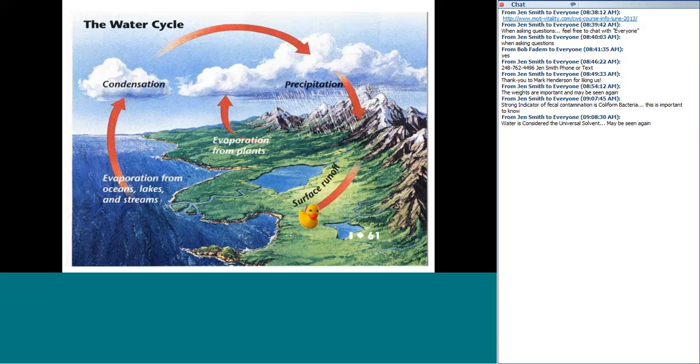We even have neutralizing. So those of you out on the East Coast that run into acid water or low pH water, that's basically when the water is acidic. It comes down from the clouds acidic because of the carbon dioxide levels, and in most areas in the country, you're neutralizing that water by running it through calcium and magnesium, which brings the pH back closer to neutral. That's basically the same thing that you're doing when you're running it through a calcite filter, those of you that are treating with a neutralizer. So the hydrologic cycle is nature's water treatment.